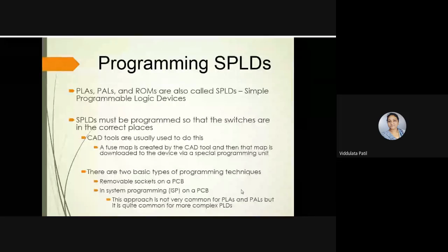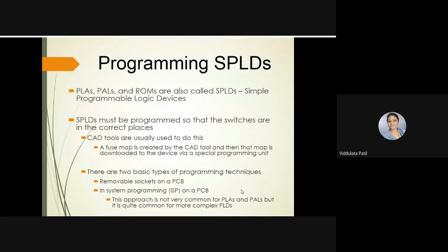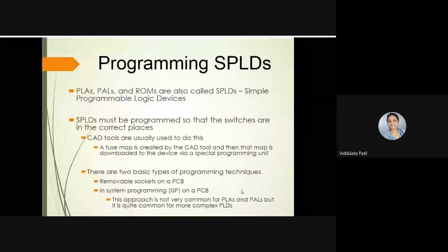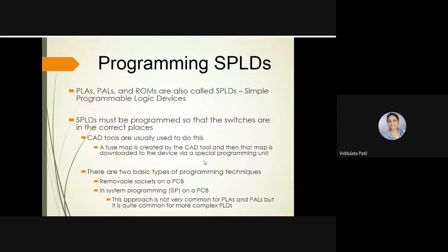Okay, now what is meant by ROM? We have not discussed it because it is a read only memory. Once we program it, it will remain the same. So what is it? These have a fixed AND plane and a programmable OR plane. Okay, so these are the ROMs. PLAs and ROMs are called SPLDs, which are simple programmable logic devices.